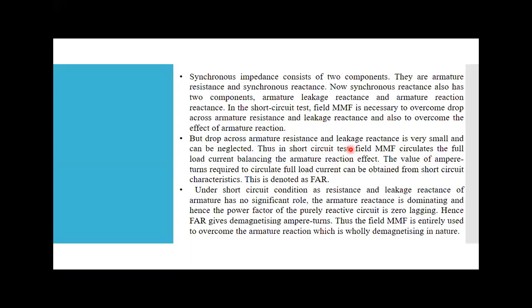So in a short circuit test, the field MMF circulates the full load current only to balance the armature reaction effect. We are neglecting the drop of armature resistance, and we are also neglecting the drop of leakage reactance. Why? Because compared to armature reaction, it is very small. So we are neglecting it.